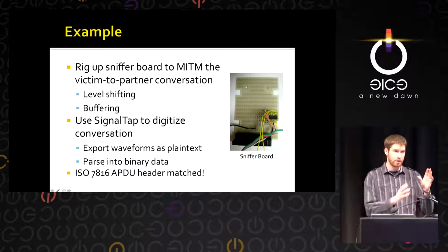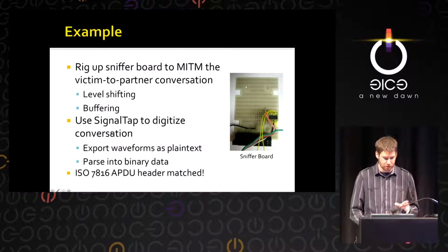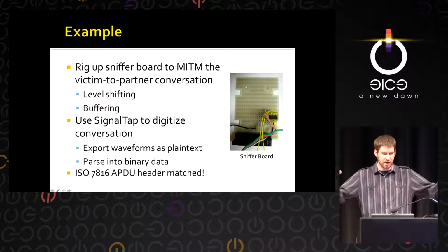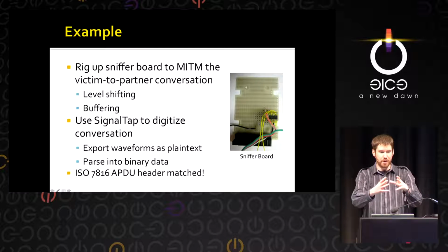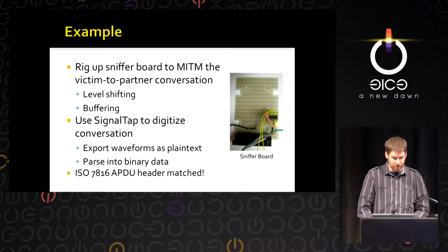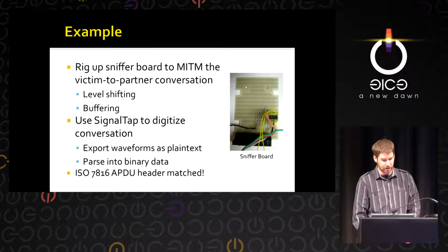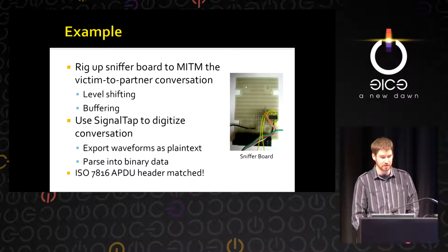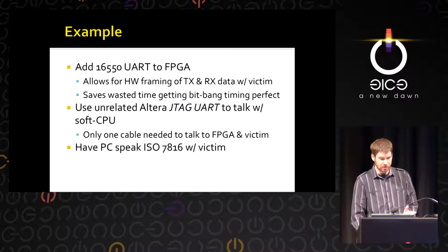So then I used that sniffer board to basically man in the middle of the conversation, and I used that Signal Tap logic analyzer software in the FPGA to export the waveforms as plain text, pack those individual bits back into bytes, read the byte string, and I found out, after Googling, that I had an ISO 7816 APDU header that I found. So at that point, this was good.